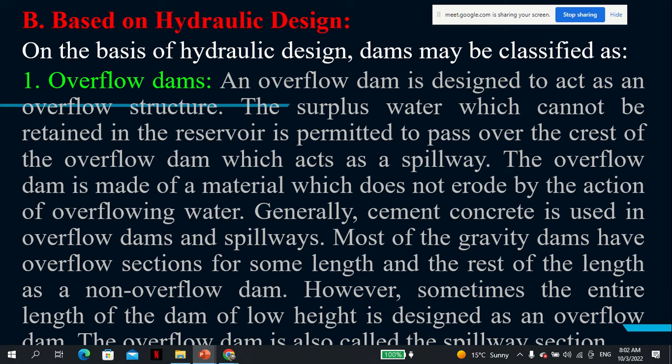So it has to be of very high shear strength, because when the water exits at high velocity, highly likely it will erode. But once it starts to erode the embankment, the people downstream may be in danger. I'm sure you've seen a lot of movies, but also actual disasters where dams have failed and downstream is an entire city. People have died, and there are a lot of case studies for this. So these are the things we need to avoid.